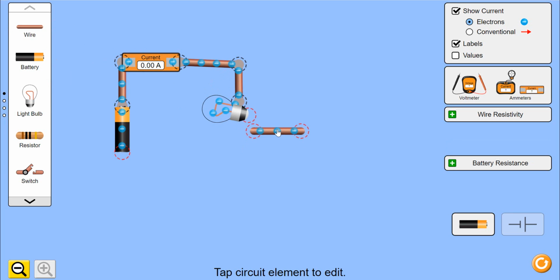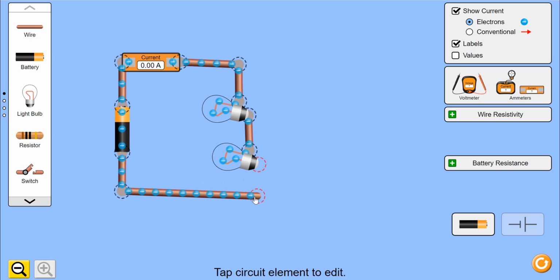Make sure as you're building your circuit, you do connect it to different sides of the light bulb. Don't accidentally hold the wire to the same end. So we have two light bulbs here. Those are two resistors down the first path. I'm going to connect the remaining here. So far, if I pretend I don't even have that parallel pathway just yet, this would be a circuit in itself. Kirchhoff would say, well, if I gain this much voltage from the battery, 15 volts, by the time I get back to the bottom, I have to use up all 15 volts here. There we go. It's running both of our batteries.